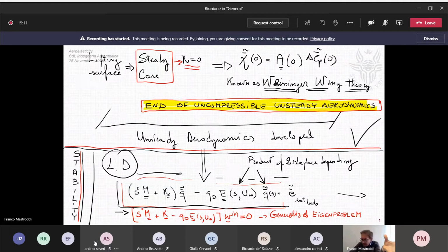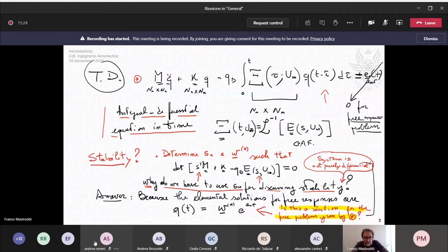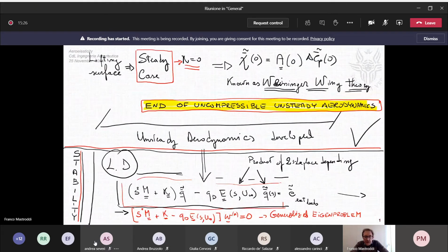Okay, so we dedicated past time to the different procedures for determining these generalized eigenvalues, as poles of our aeroelastic transfer function matrix. And we discussed that we have an iterative possibility and a standard possibility based on the use of finite state representation for the aerodynamics.